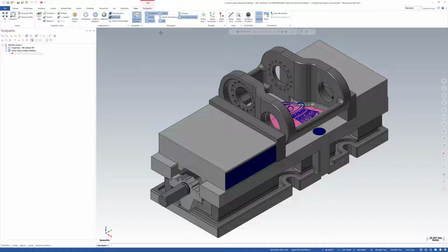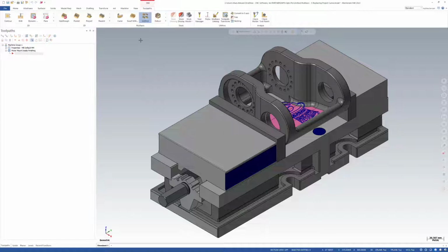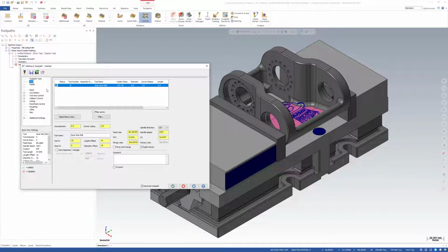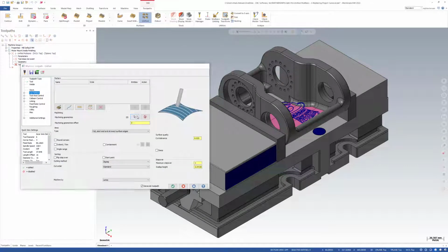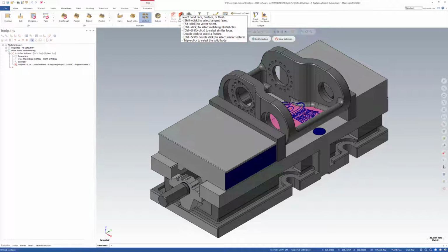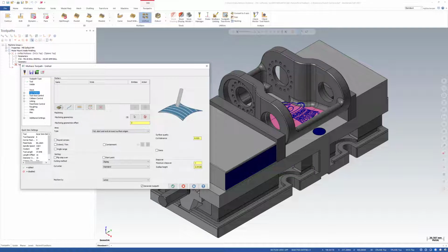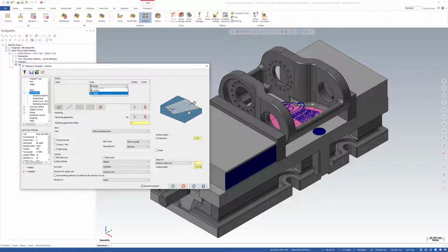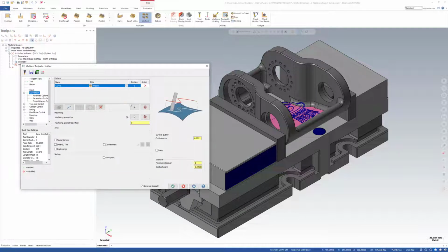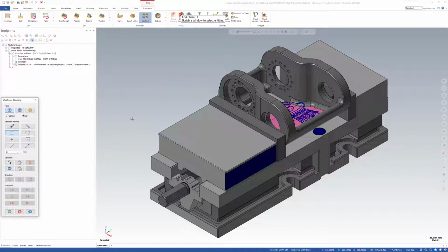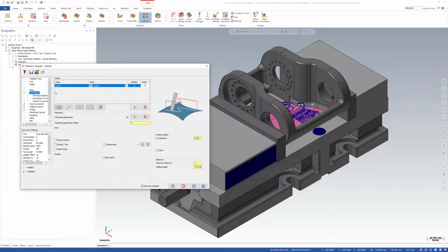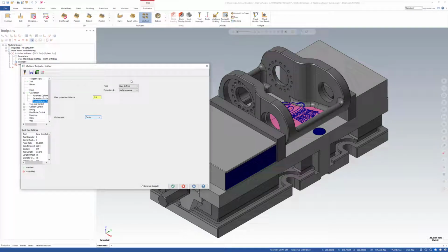So the next thing we'll do here is create a project curves toolpath. So let's go unified, same ball end mill, and the same drive surfaces. So we'll grab our pink surfaces. And then some curve inputs. You'll notice we can select project. And when I window the logo, you'll see down here the familiar settings for the project curves toolpath.